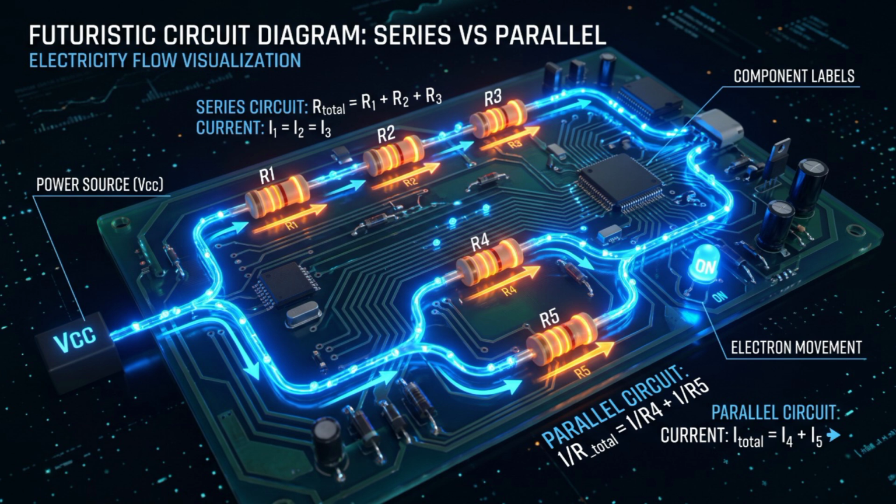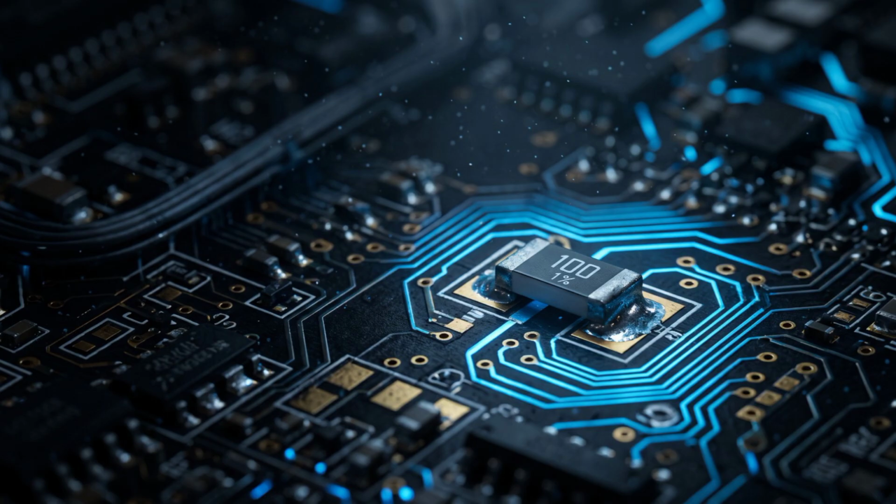But what if there are no color bands at all? Welcome to modern electronics. These are SMD resistors. They use numbers like 103. That means 10 followed by 3 zeros, 10,000 ohms.